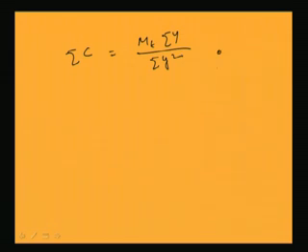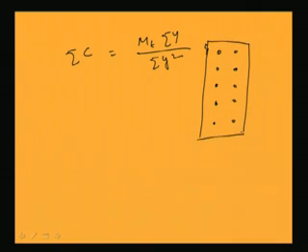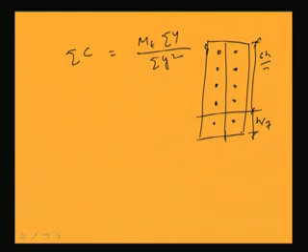Now, if I see the diagram, if the rivet groups are like this, and suppose this is the plate, now this is the neutral axis where it has passed. So, this is basically h by 7 and this is basically 6h by 7, these are the assumptions. So, from this I can say that when we did the stress distribution, we have seen that this will go like this.